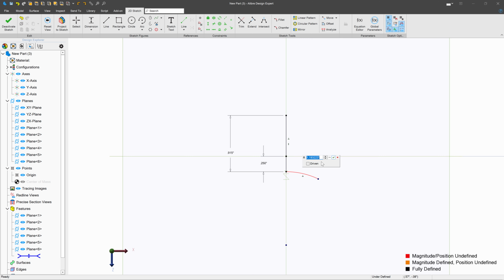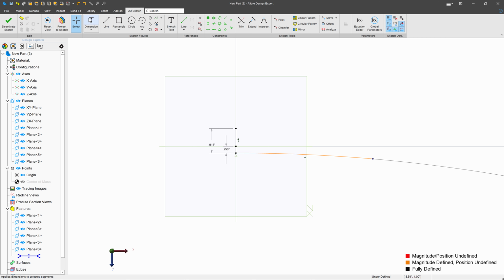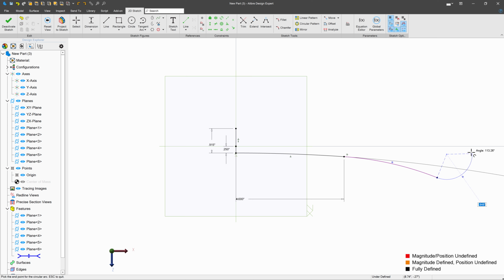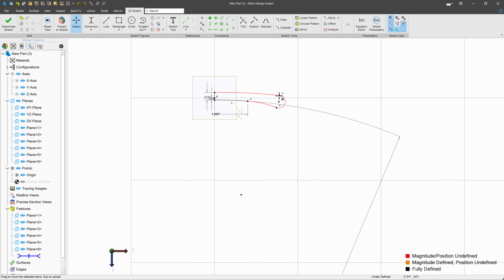Next, we'll give this arc a radius, and we'll give it a radius of 58, right? Relatively large radius. I'll probably constrain this horizontally from the origin at a distance of 4. And then we'll give this a tangent arc, and then another tangent arc where we can come back around, and another tangent arc where we go back to the line that we started from. So everything's all tangent, but I do want my arc center here to be vertical with the origin.